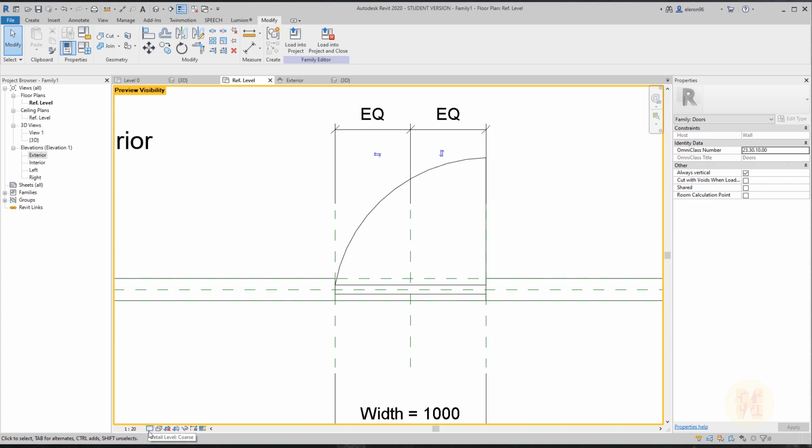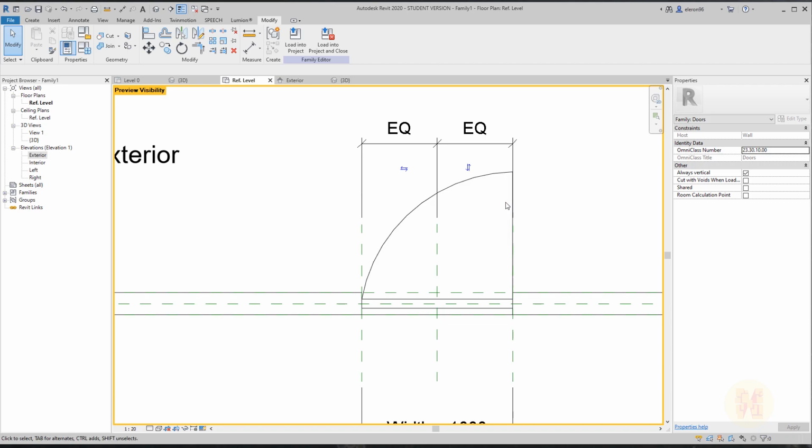So as you can see, here is the coarse, and I can see my door opening. I will change it to medium. I cannot see it. To fine, I cannot see it, and to coarse, I can see it. The reason why you can place in one location a few different types of detail of your door is this. For example, here is just a line. After that, you can draw a more detailed door with some opening, with some interior things, for example, with the handles, so up to you. But you can just manipulate it with the detail level.